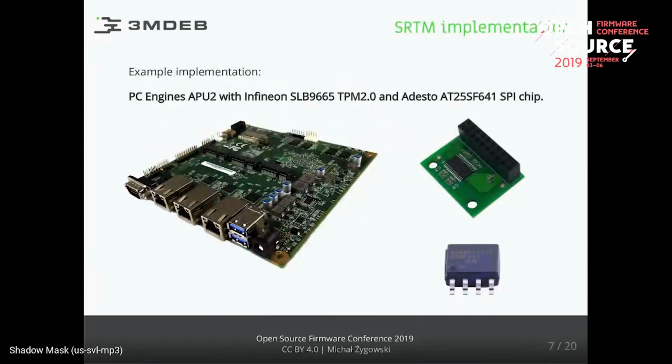My implementation is based on PC Engines' APU2 platform. The TPM module is an Infineon SLB, as presented on the slide. And the flash chip I have used to implement the permanent SPI flash lock is from Adesto. It's an 8 megabyte chip.